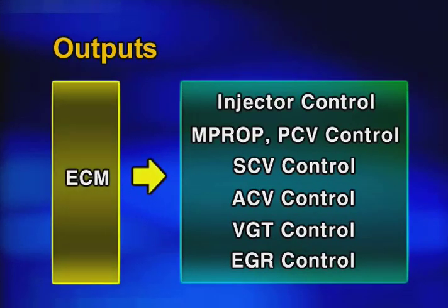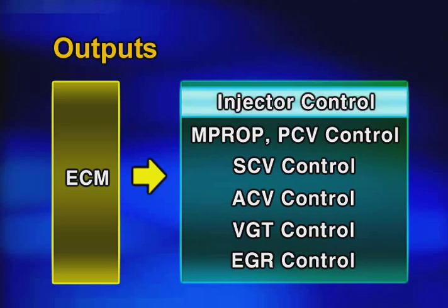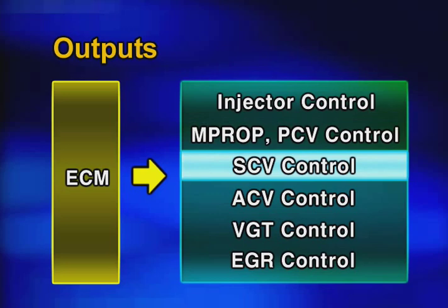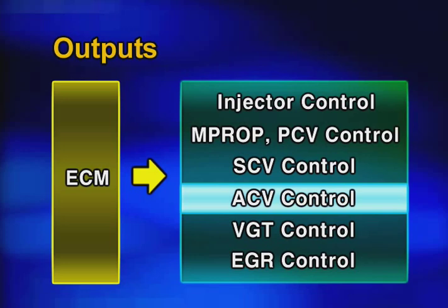The ECM, receiving the signals from the various sensors, conducts the fuel amount control for changing the fuel injection timing and amount at the injector, the fuel pressure control for controlling the pressure generated by common rail at the dual pressure control valve, the swirl control valve control for enhancing the output and reducing the emitted particles by varying the intake manifold path according to the engine load,